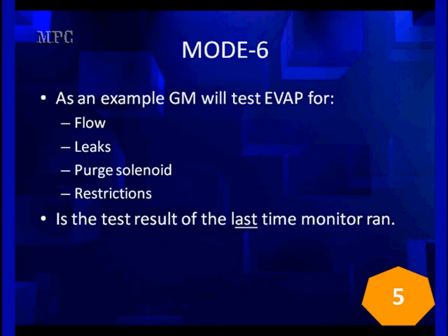The temperature must be between 40 and 95 degrees at the time the vehicle started, and both the intake air or ambient air and the coolant temperature must be very close to each other, 10 or 15 degrees. That means you're going to get one chance to run this in a day, and it's not going to be a vehicle sitting outside in the wintertime on a really cold day where it's below 40 degrees when it starts up in the morning.